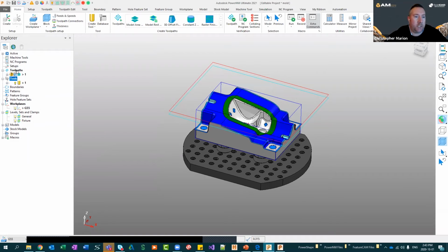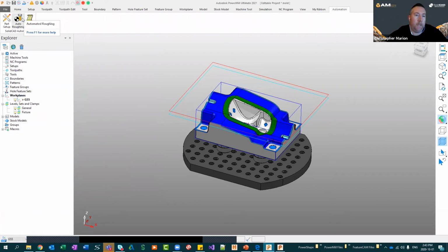So let's go ahead and delete that toolpath, delete the tool. And what we're going to do is run this macro, which will import each template one at a time. It will also ask me to create a stock model. If you're unaware what a stock model is, think of this as a representation of where we are in time on our stock. So it's a stock management tool. It's going to show me where we're at in time. It's also going to allow me to take the next toolpath and refer to that point in time, and it's also going to allow me to review where the stock lies at that point in time.